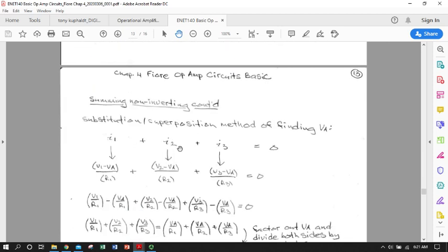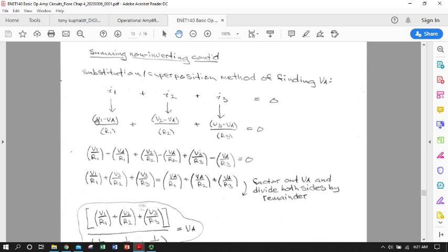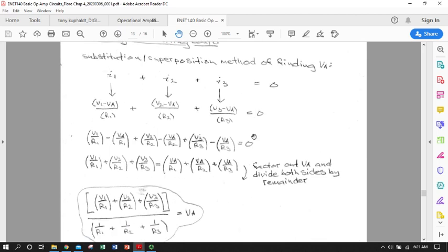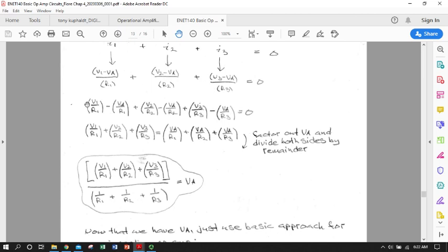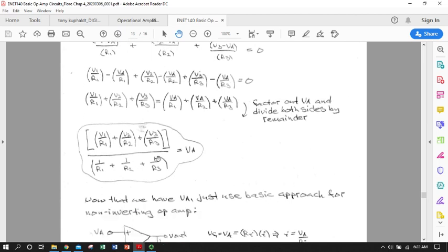And so we write that for each one of our currents, add them up. Because we added up the currents, we add up the current equivalent expressions, and you'll notice we've got one equation with only one unknown there. So if we distribute R's, do some algebraic simplification, we can get a single expression that has just our R's and our V's and get our voltage at point A.